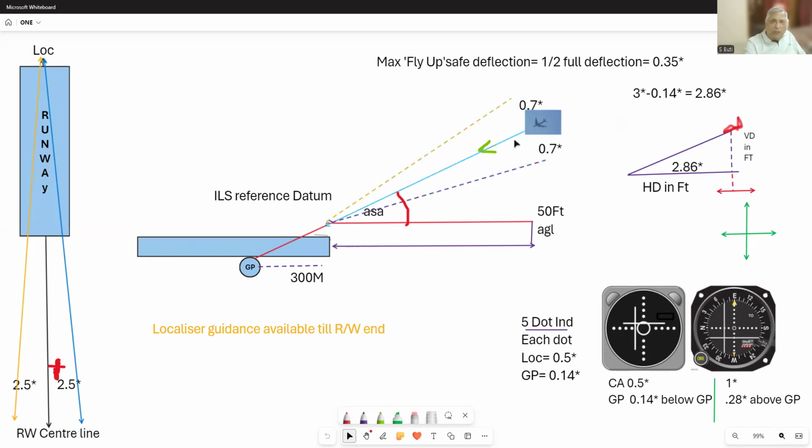And this particular line on which you'll make a descent is called the approach slope. The standard glide path angle between the approach slope and the horizontal is 3 degrees. There are places where there is an obstruction somewhere short of the runway, then this angle may be increased slightly.